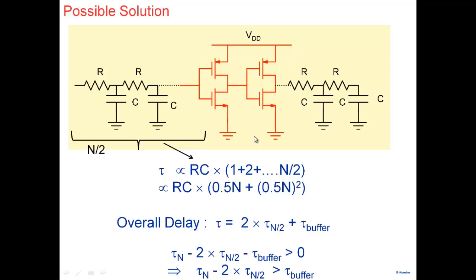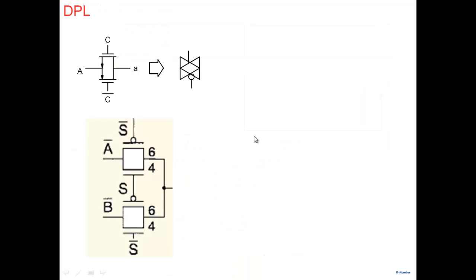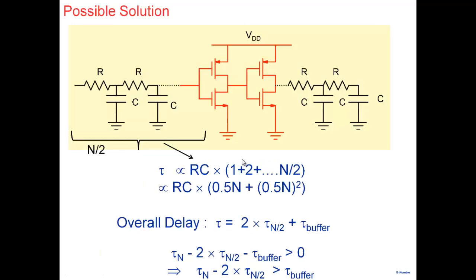So if you continue thinking along those particular lines... Sir, yes. Can we not replace this buffer again by a capacitor and resistor and it will be same as before? Can this buffer? Yes. No, so note that if you look at here, there is a signal which has made a transition. So it goes RC, RC, RC here, and then when it comes here, all that it sees is a capacitance at the input. It sees a capacitive loading and it stops here.